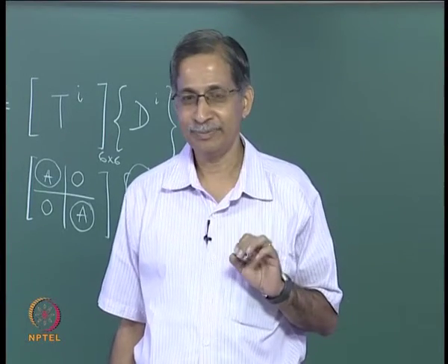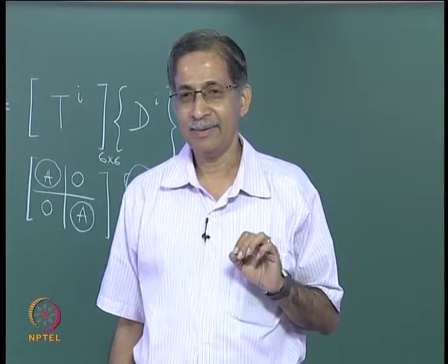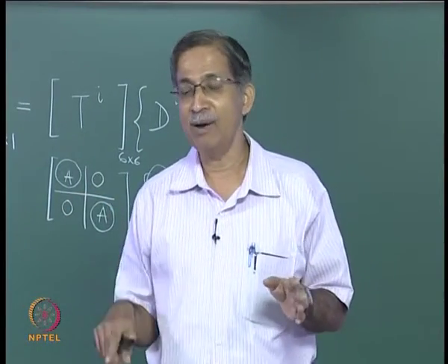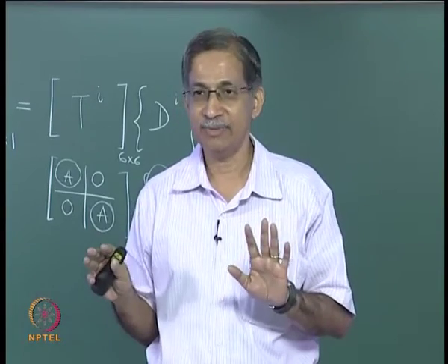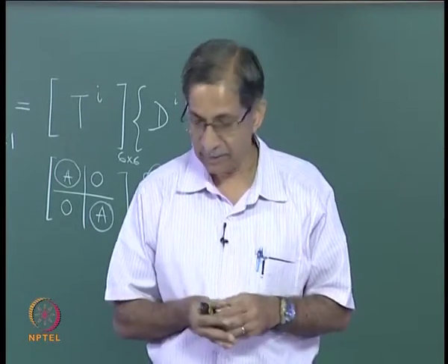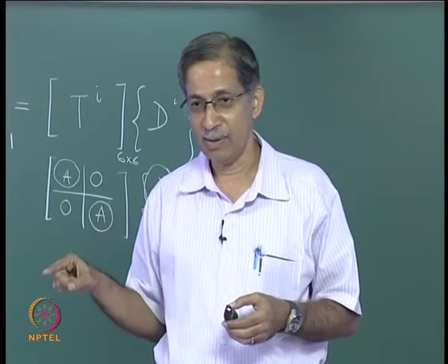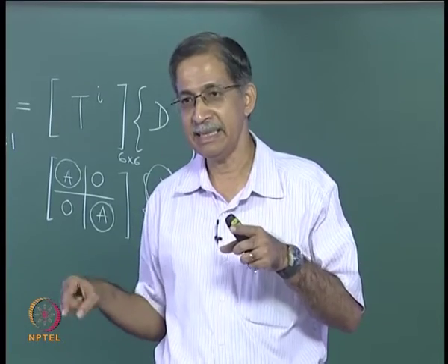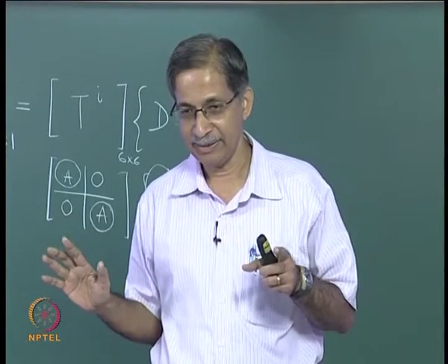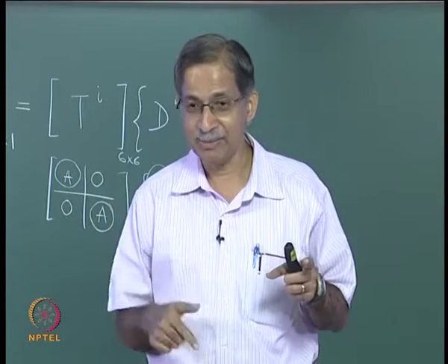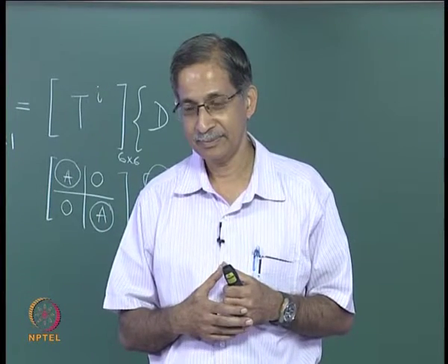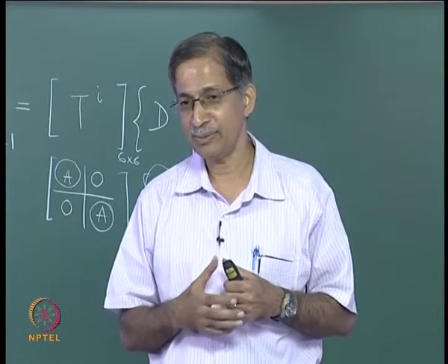Let me give you a clue. First we began with a structure. In that particular frame, how many displacements did we have? We had 12, dA and dR, right? We had d1, d2, d3 all the way to d8, they were active degrees of freedom, and d9, d10, d11, d12 were restrained degrees of freedom. How are those linked with these?